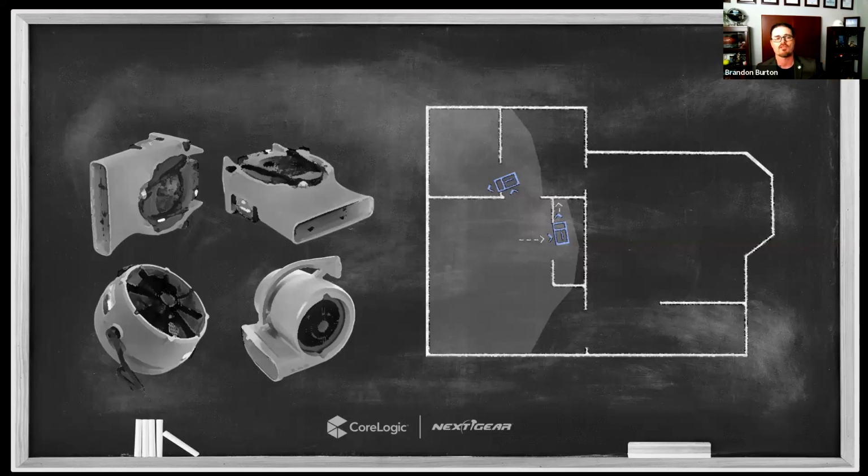These are great because they have really good energy efficiency, which to me is probably the number one limitation to that initial air mover installation, is that if you're using air movers that aren't very energy efficient, in many cases, you're going to run out of power availability for what you need for that first 24 hours of drying. So using something like a low profile air mover where you're getting 1,000 CFM for only like 1.5 amps, somewhere in that neighborhood, is a really, really good use of energy that's available inside the property. It can run a lot of air movers on a circuit that way.